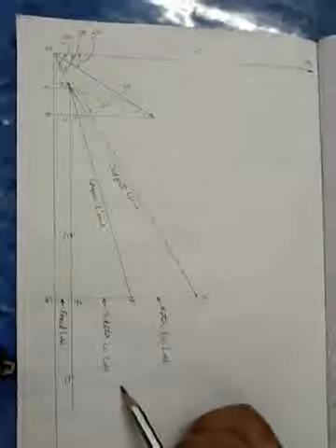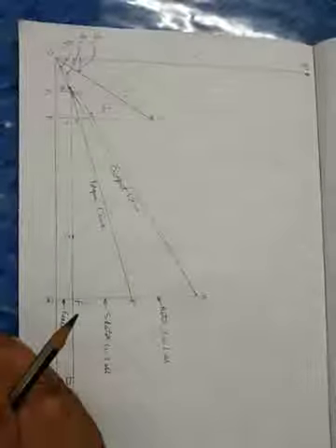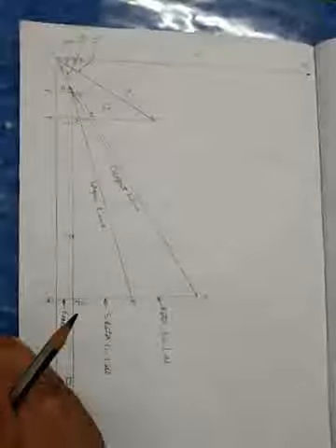The upper part is the rotor copper losses and the lower part is the stator copper losses. When the rotor is locked, all the power supplied to the motor goes to meet core losses and copper losses in the stator and rotor winding.